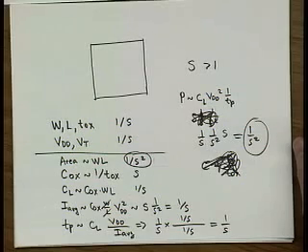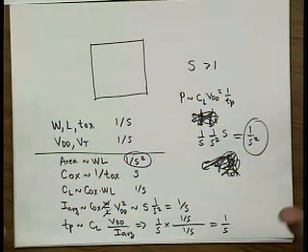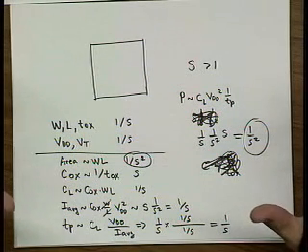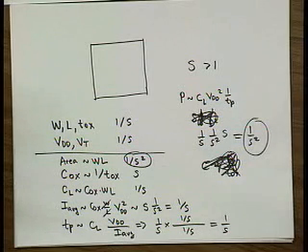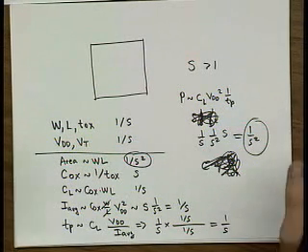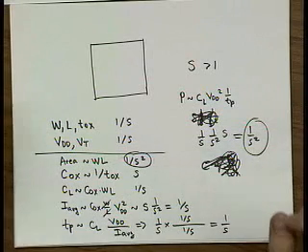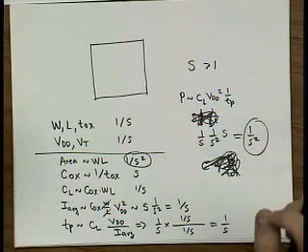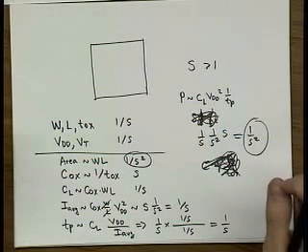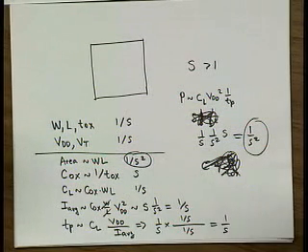The problem with this trend is that this model is ideal when you assume that everything scales by the same factor. Later on we will come to the fact that, due to velocity saturation effects, you have to scale your voltages and your dimensions by different factors for speed reasons and also for power reasons.